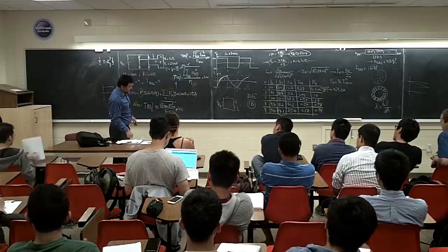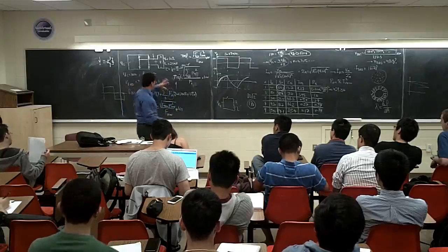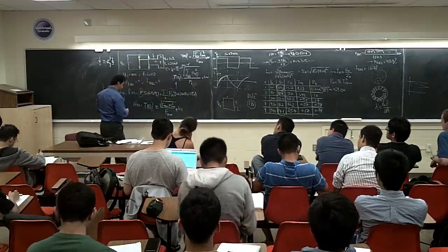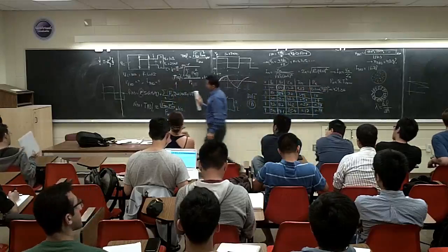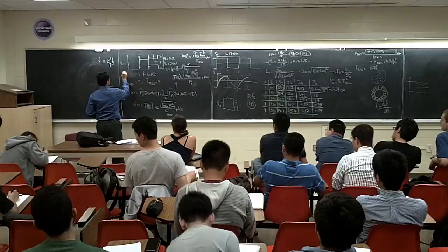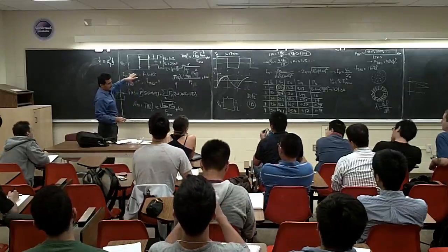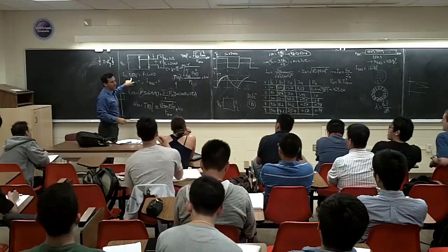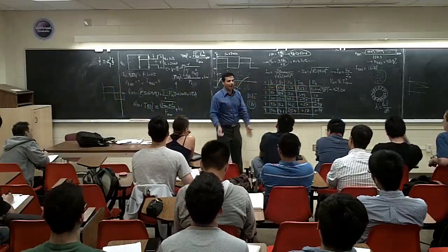Yes. So what he explained here is the ideal example, the next example. He said we have a full bridge inverter with this much R and this much L, and usually it's not like this, but instead of giving us the DC bus, it says I want to have this much current for my first harmonic, basically matching this number. He said I want to get the same output power.